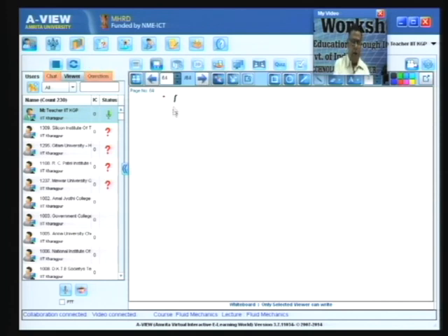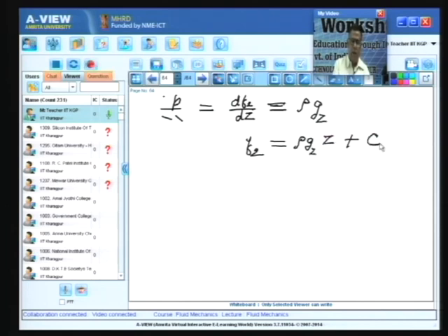Now, let us look at the third equation, del p del z. This will be d f 2 d z, which is going to be equal to rho times g z. So, if I integrate this, you are going to get f 2 is equal to rho g z, which is a constant, multiplied by z plus a constant of integration, because this is a total derivative. So, if I take this expression for f 2 and substitute into the expression for p, we are